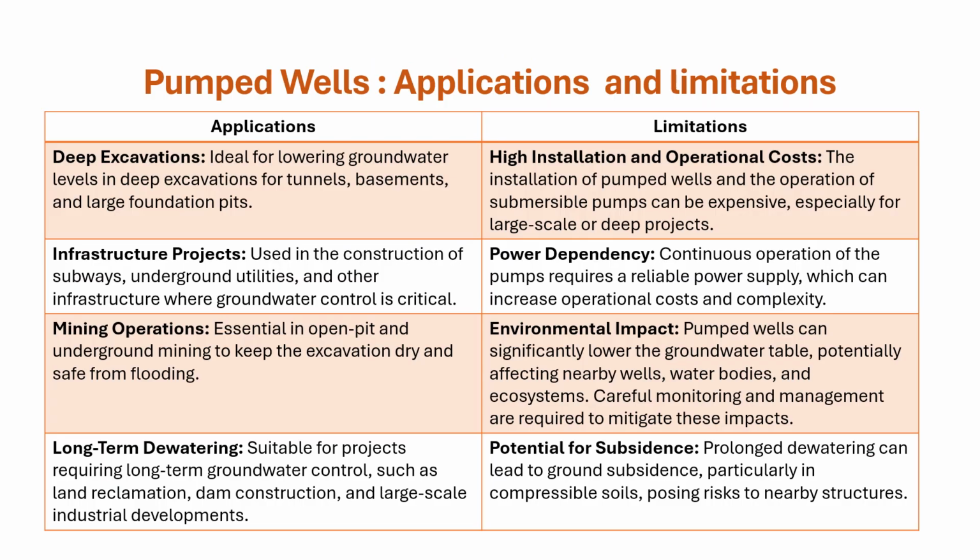Pumped wells are very useful for deep excavations, or as I said before, for infrastructure projects, for mining operations, and long-term dewatering. However, they have some disadvantages, such as the high installation and operation costs, the power dependency, and the high environmental impact.